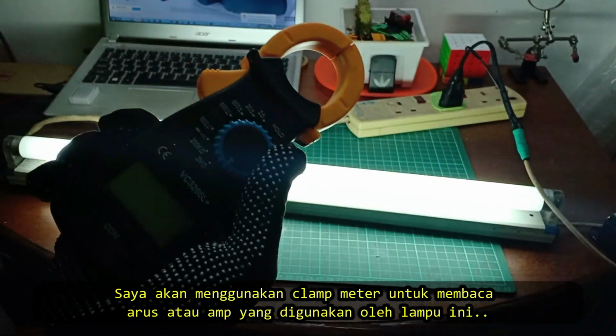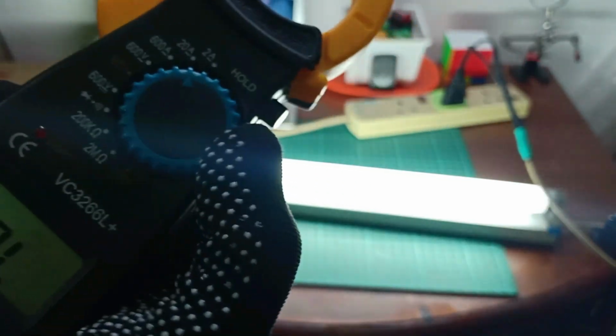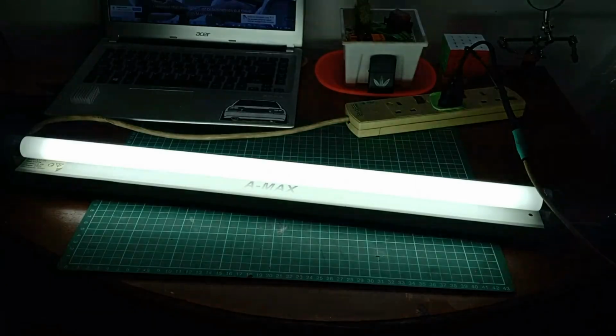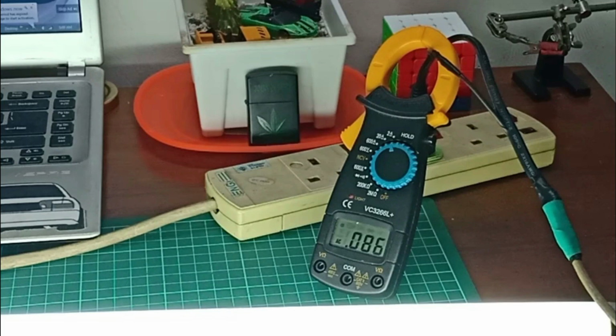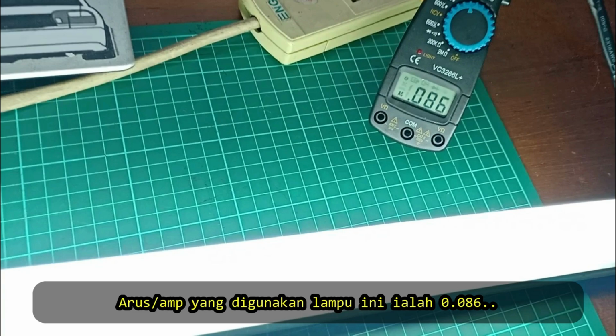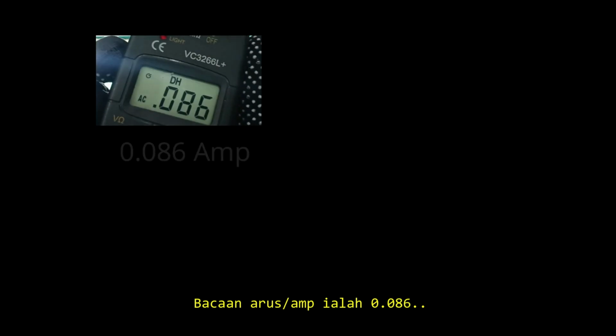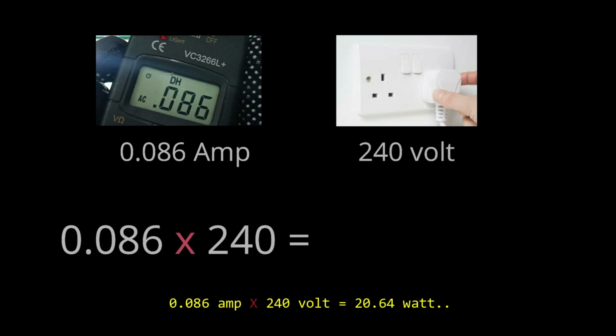I will use a clamp meter to read the current or amp used by this lamp. It reads 0.086. The current or amp reading is 0.086. And volt from the wall plug is 240. 0.086 amp multiply 240 volt equals 20.64 watt.